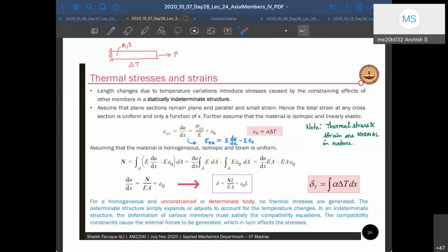So, did you ask stress or strain? Yes, stresses. Okay, so for stresses, we have to see the internal force there and then the area of cross section. So what would be the internal force? We have to write the equilibrium for that section and then try to find out the internal force there. Okay, so some of you have already answered that it should be P by A.